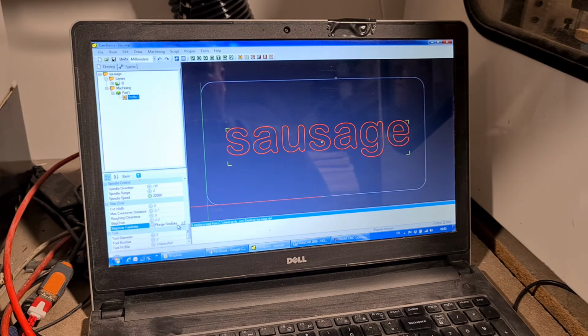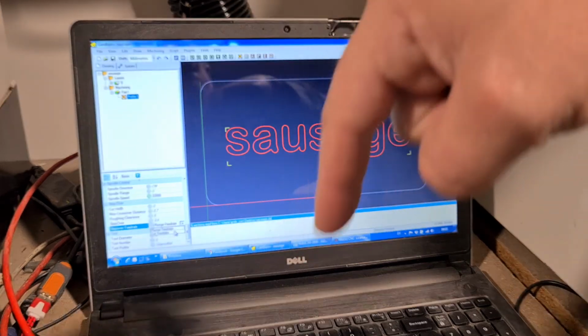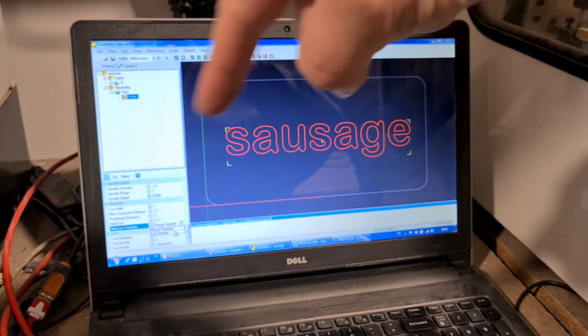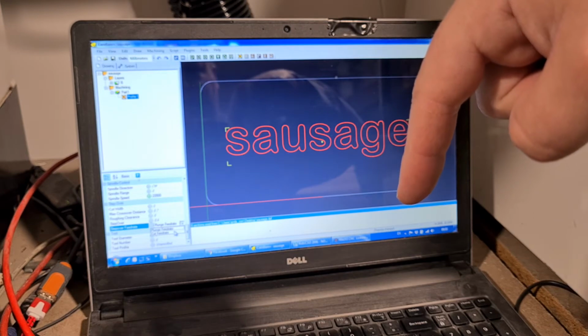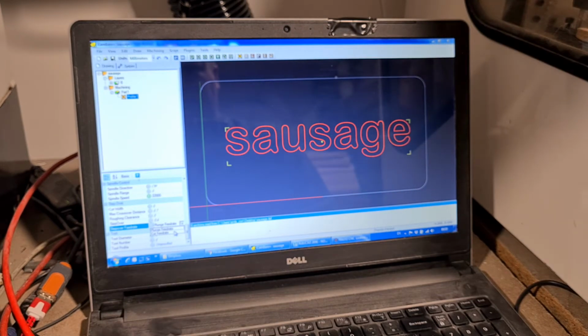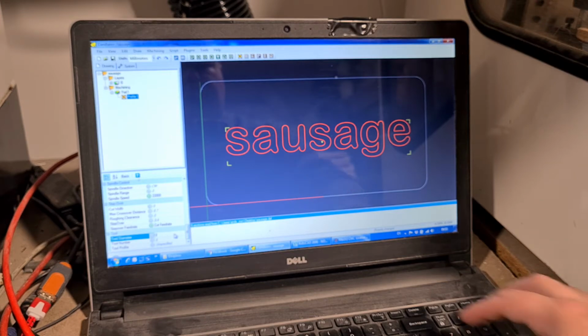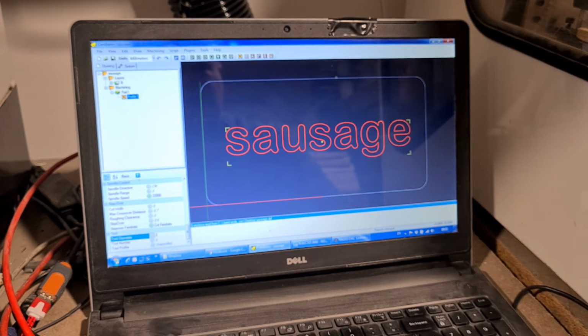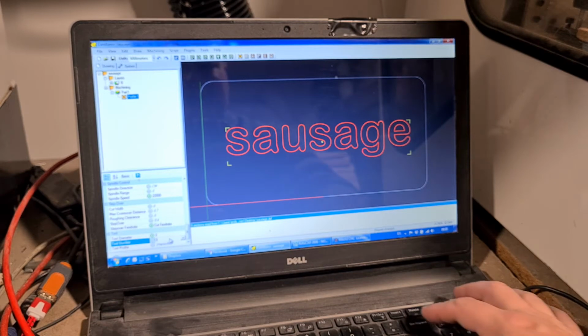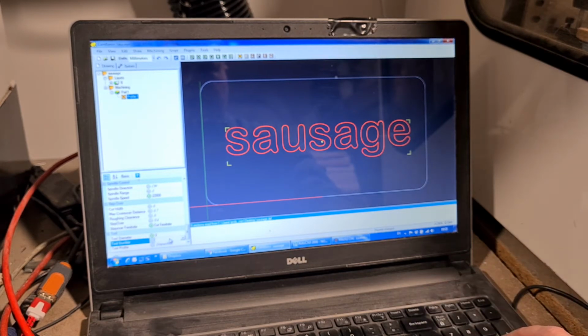On this particular, I could be using a profile. This is how fast a step over. So once the tool's gone round and cut out and it moves over to do its next pass, it's how quick you want that step over. There's no need for it to be a plunge, it can be a cut feed rate to make it fast. Tool diameter, we'll go for a 2mm tool, and because you've got an ATC, you'll be using the tool number. For this we'll just do a tool 1.